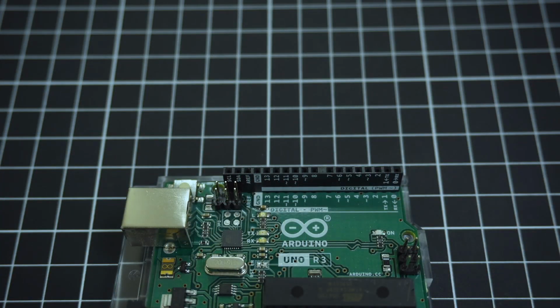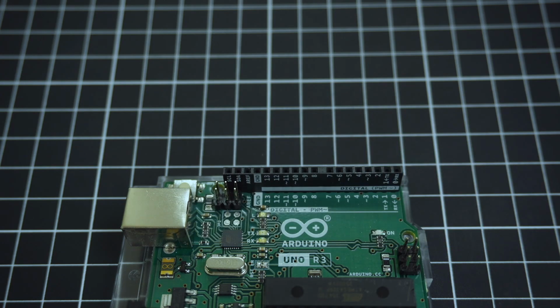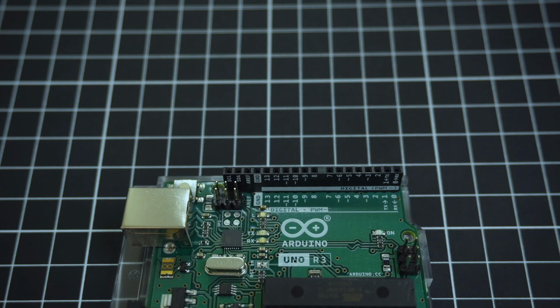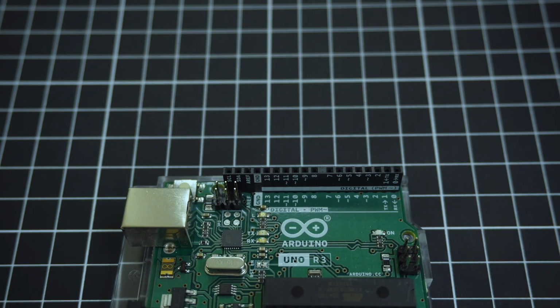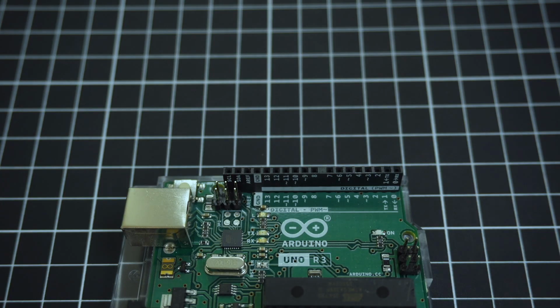On one side of the board, you will find 14 digital input and output pins, labeled from 0 to 13. These pins can be used to read digital signals, such as high or low, or to control devices like LEDs, buzzers, and relays. Some of these digital pins also support PWM, which allows you to simulate analog output. These PWM-enabled pins are marked with a tilde symbol next to the pin number.